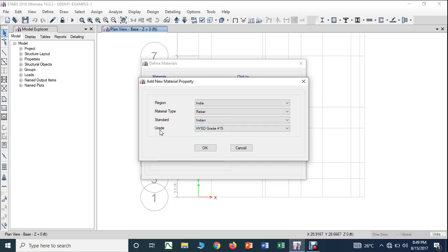Now you can see, as I told you, when it comes to rebar we usually have three: mild steel, which gives a characteristic strength of 250 Newton per mm square. Then next you have HYSD. In that HYSD you have two grades: one is Fe415 and one more is Fe500. Fe550 has been recently introduced, and in the software it is not yet incorporated.